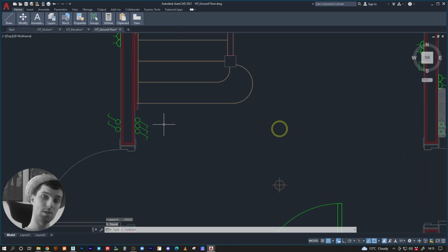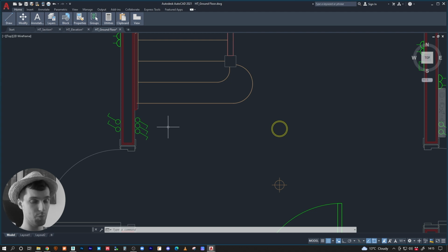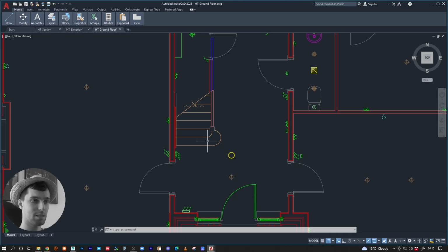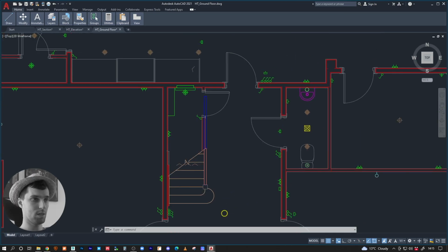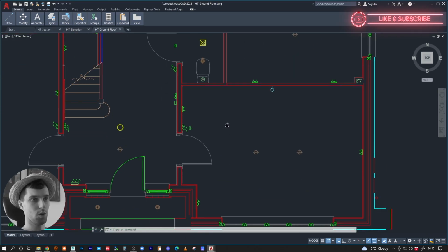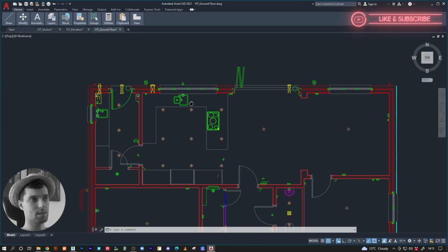If you select an object and press select similar, space will not work anymore, because space will actually do the same, select similar, because what space does is repeat the previous command. So whatever previous command you did last, that is your previous command, right? So use delete and the space button. You will get along with this. It's just gonna take a little bit more time to get used to. That's about it. But basically this is clean enough.